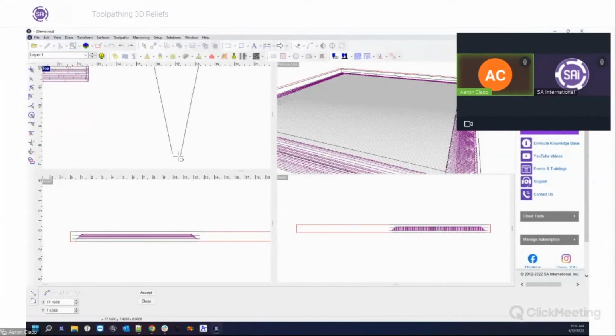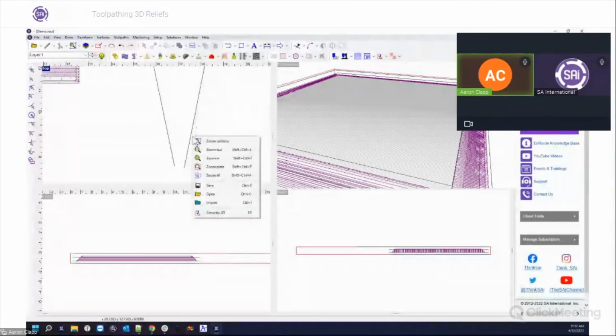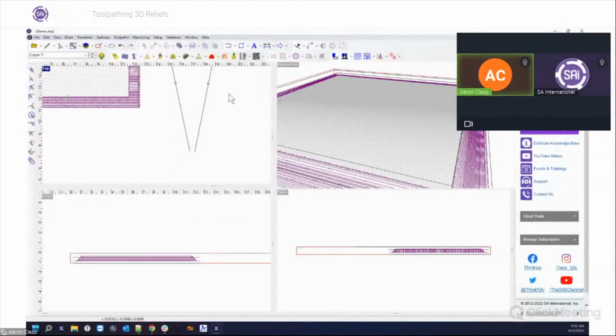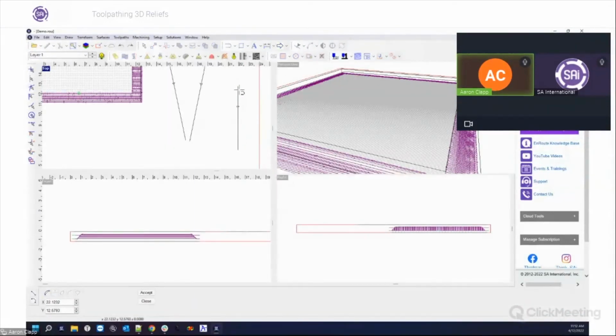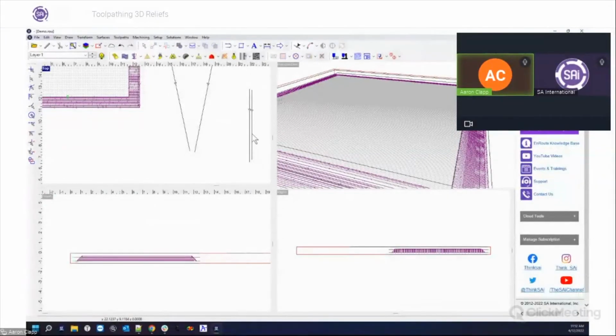Those 1/8" bits are a little bit more resilient than others. The reason why I say that is because obviously the shaft gets thicker as it goes up, versus if you're talking about a tiny little 1/8" end mill, you've got a tool that looks like this. It's super narrow and super flexible.